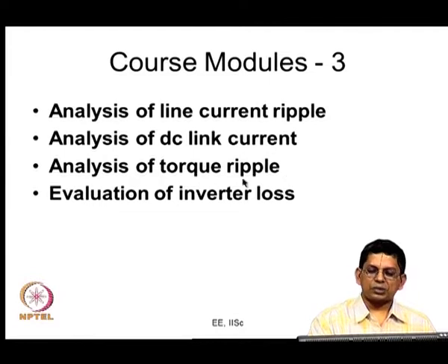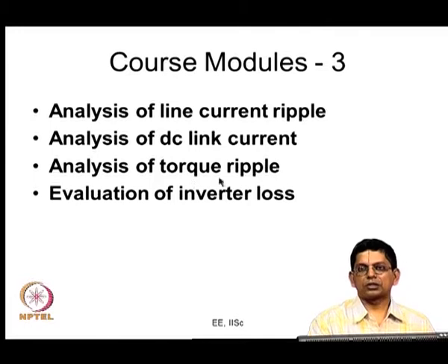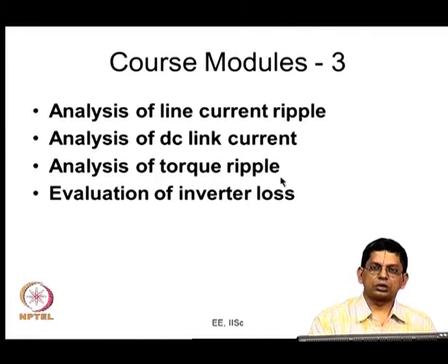And in the high frequency case, we looked at it as the integral of error voltage. We considered the error voltage vector and integrated that to get the stator flux ripple vector, and we used the q axis component of that to do this job.